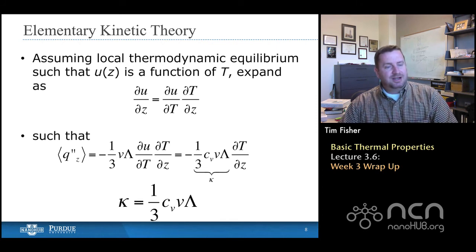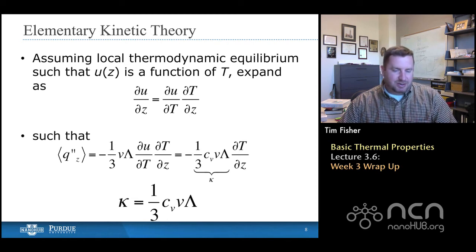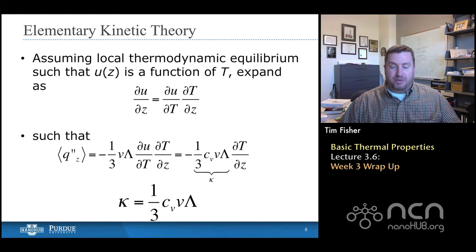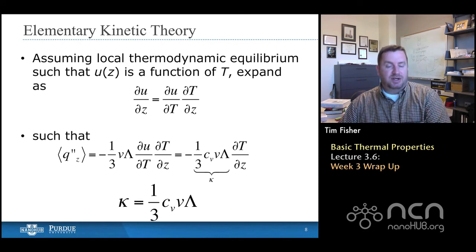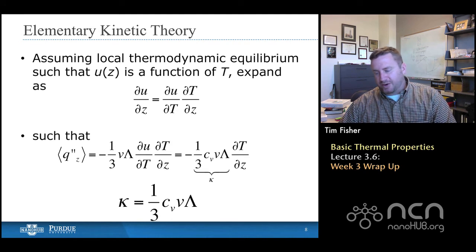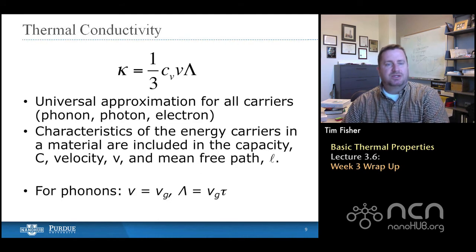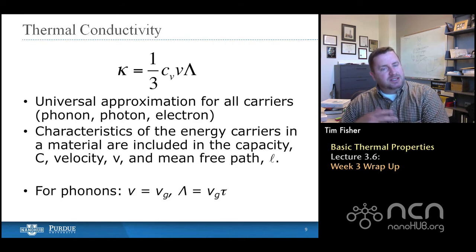Again, the thermal conductivity is the star attraction often when we're solving or modeling a heat transfer problem. And this is a way that we took a property that we had derived for different carriers, the specific heat, and used it intimately in the definition of thermal conductivity. So that's why we did these derivations in the order that we did. And this thermal conductivity is the kinetic approximation for thermal conductivity.